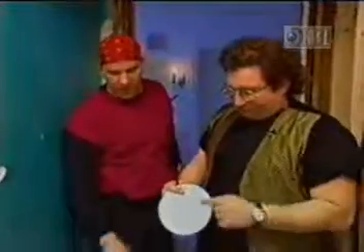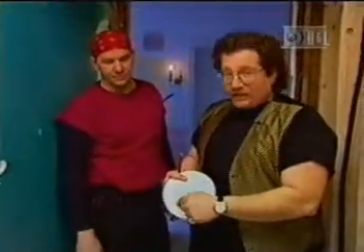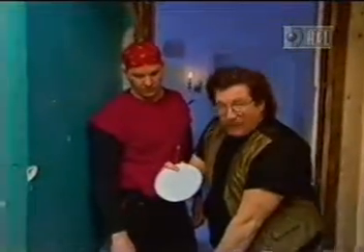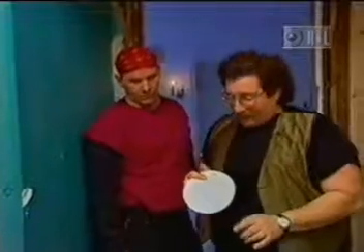Inside every recessed light, you're going to find a template like this. It's got the instructions on it, and this template itself is also just a tiny little bit bigger than the recessed light itself. So after you cut through that center hole, you put this right on there and you trace around it, you cut that, and we know that it will then fit.